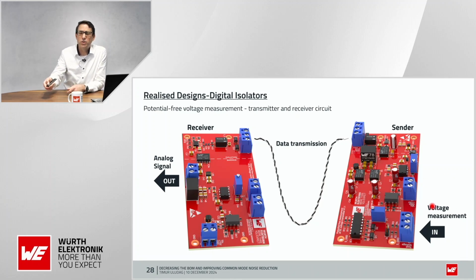Here you go for the voltage measurement, so you measure a battery in a stationary battery compartment. Then the signal is going through the twisted pair cable, and then out to the operator.